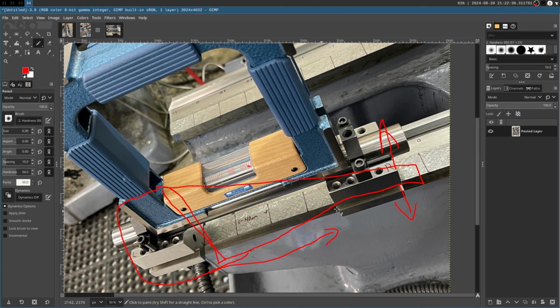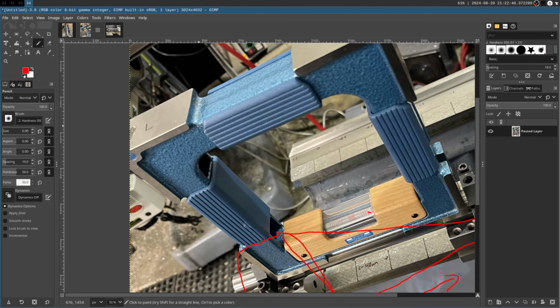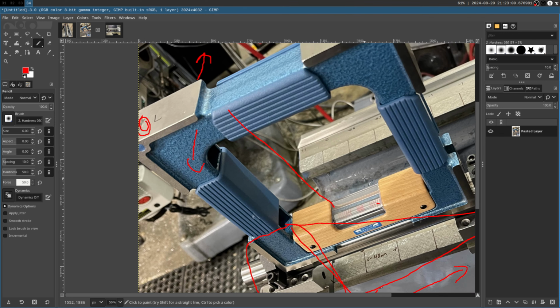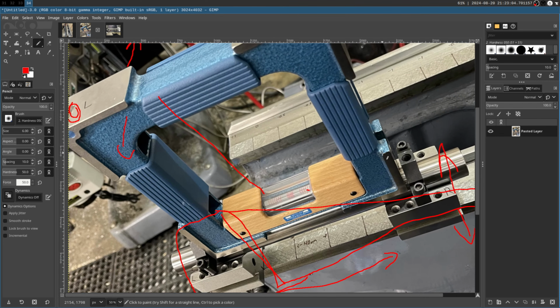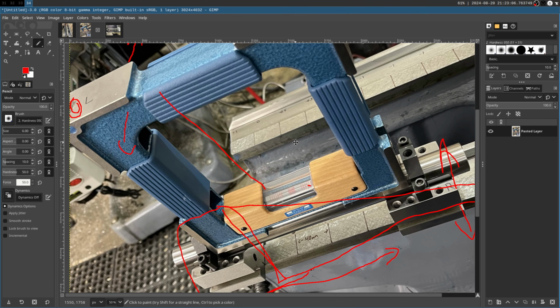But the stack up above, and I have another bubble here that's not a super accurate level, but I use that to make sure that the level is level in this dimension, such that we're sitting basically flat up and down on the bar, and we're not twisting the level, right? We don't have the level laying down on the other bed when we take the measurement, right? So all of those things cancel out a lot of the errors that we have.